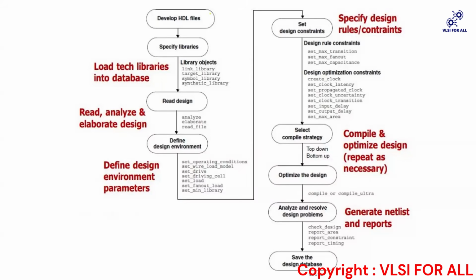So we have developed the HDL file, we have loaded the libraries into the database, and now we have read the design. Let me give you the command read_file. The read_file command does analyze and elaboration together. Now let's see the next step, that is, define design environment.